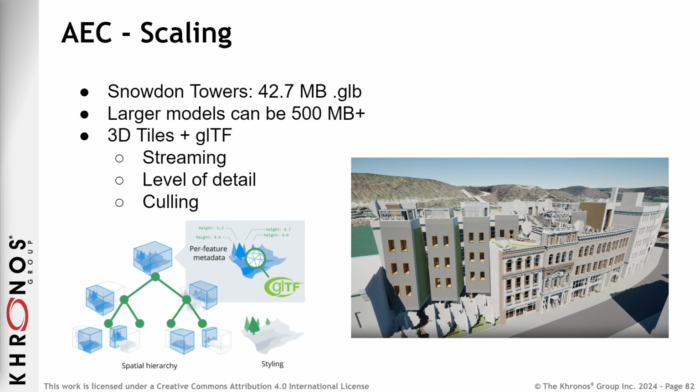In terms of scaling, this example, the Snowdon Towers example, is a sample project in Revit. It's a 42 megabyte GLB file, but there are often a lot larger models. This is on the smaller side, and we can easily see models that are 500 megabytes plus. So for that, we utilize 3D Tiles, which is built on glTF. It provides a spatial subdivision of glTF and has a bounding volume hierarchy. It enables you to stream the data, and also enables level of detail and runtime optimizations like culling.